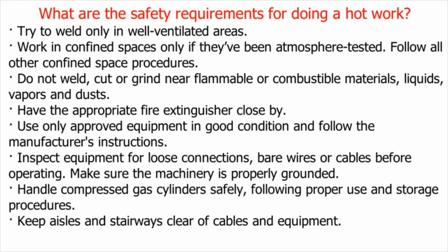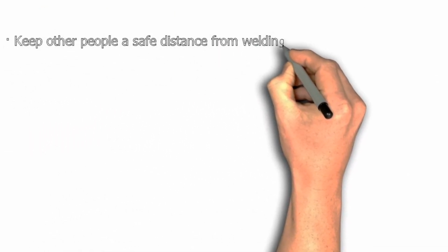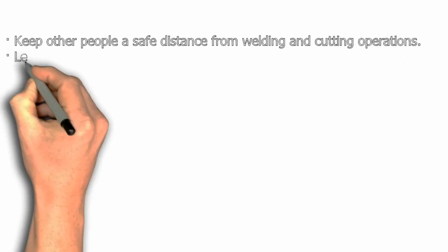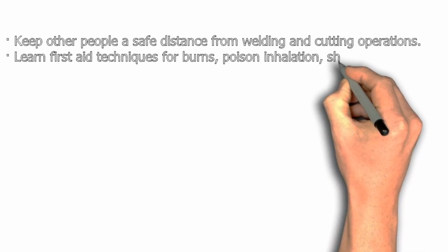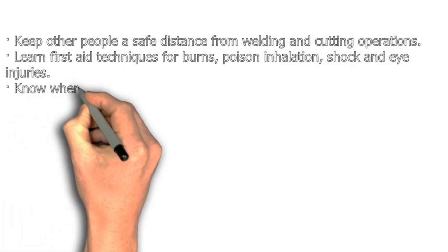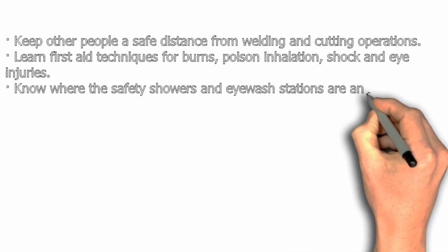Keep aisles and stairways clear of cables and equipment. Keep other people a safe distance from welding and cutting operations. Learn first aid techniques for burns, poison inhalation, shock and eye injuries. Know where the safety showers and eye wash stations are and how to use them.